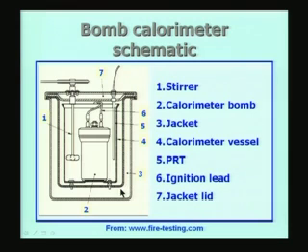This is the important thing to remember. So, in this experiment there are two parts. In the first part, I am going to use a standard material. Usually the standard material used is benzoic acid, whose calorific value or heating value has been accurately determined by various laboratories, and the value is available to us.